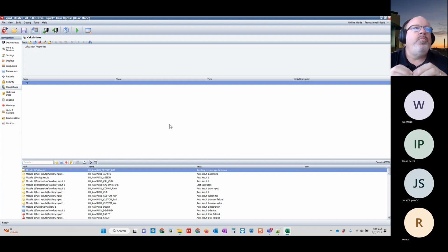There's a bunch of different ways that statement can be written, and if it works, there's not necessarily a wrong or a right way to do it, because there are several ways that I can do this. So for simplicity, let's make this really, really simple. We're going to look at digital 1. When the signal state of digital 1 goes high, we're going to set digital 2 on. When the signal state is low, we're going to set digital 2 off.